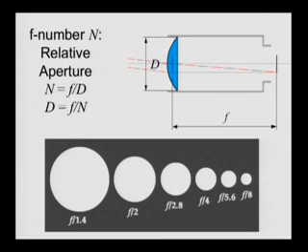There are standard scales, essentially labeling by different conventional roundings of powers of the square root of 2. The square root is in there because the area is doubling for each increment here, since the area goes as the square of the diameter.